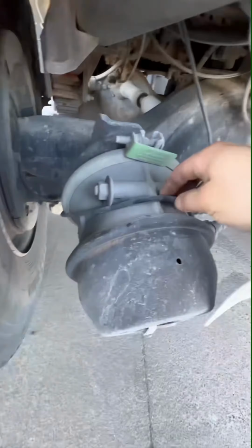What in tarnation? You said the light was not on before? No, that's why I'm upset. Well, here is your problem, bud. The speed sensor wire is jammed in between the brake chamber and bracket. This was not part of the fan clutch replacement we did. Whoever installed this brake chamber created this issue. Plus, we asked you if you wanted us to look into the ABS light that was on before, and you said no. Oh. Oopsie.